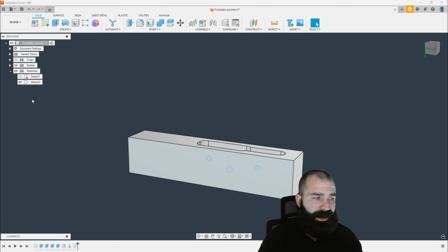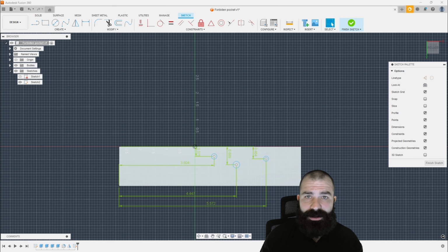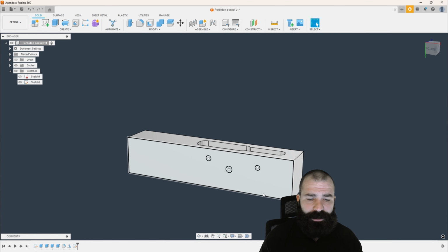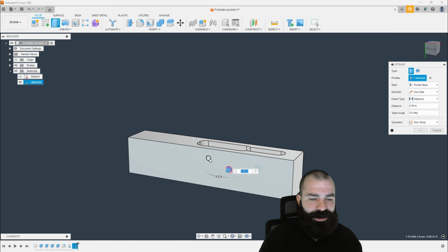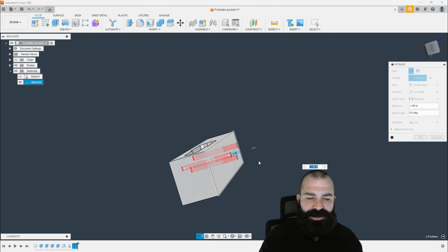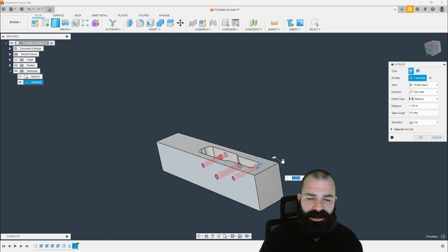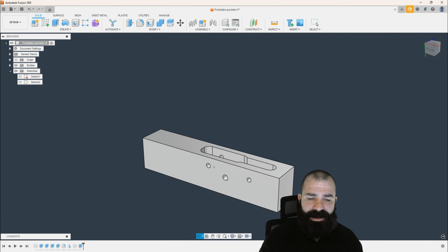Same thing would apply in my case: I would possibly go in and set the dimension of the size of these holes. Again, this is not super important for this demonstration because we just want to create the actual pocket. And I want you guys to be able to go out and draw this stuff as needed. So as you're seeing here, I'm picking those 3 shapes. They are through holes. They go fully through this body. So I can actually click this back face, and as you're seeing, it's automatically setting that to that 125 depth and creating that extrude.